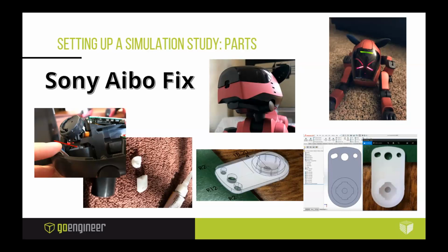I went ahead and we're going to try to run through a little example of how I set this thing up. Ideally, yes, this is going to be a dynamics application, right? It's an impact that happens. So I'm making some assumptions and I'm starting simple. That's the workflow, right? You start simple with your study types as well. And then, in the second phase, if I needed more detail for this analysis, the next phase would be to do a dynamic analysis and impact testing, shock response or something to check it out.